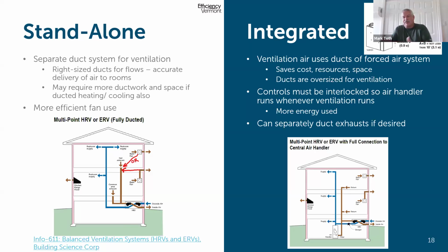Yes, that costs a little more money to run that fan, but I think if you did the math on it, creating a whole other duct system will be thousands of dollars, and integrating this, running that fan for an extra 20 or 30 minutes of every hour on low speed, that ECM fan, I think you're going to be at a very low electrical cost, and it would take you many, many years to ever reach the point of paying for the entire separate ducted system.